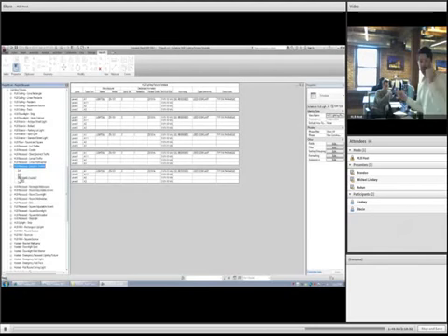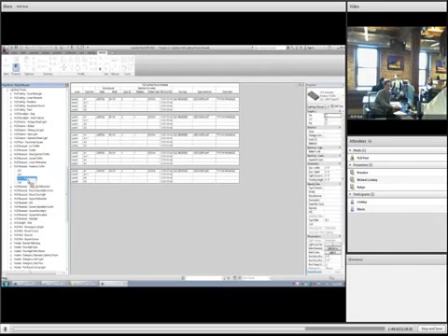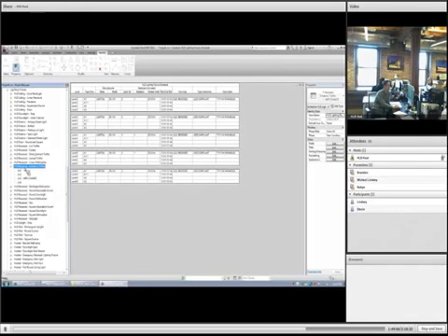Yep. Well, there's a few ways you can do it. You can name a type under the initial heading, so we could rename that duplicated one to F2 or F1, or we could rename the whole recessed parabolic troffer family F2. Maybe that's where we create that duplicate of the entire family at the beginning and say that's now called the F2 series.